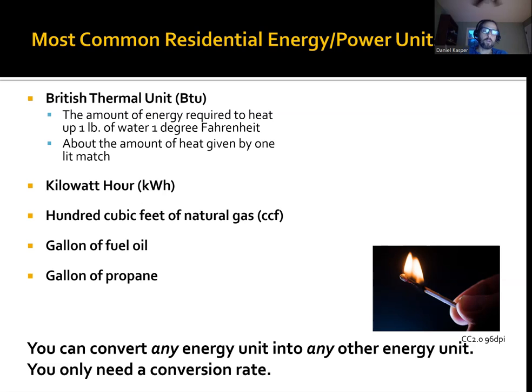For our purposes, it doesn't matter if the water is, let's say you have 1 pound of water that's 100 degrees. If you add 1 BTU to it, it's going to be 101 degrees. In order to drop it to 99 degrees, you need to subtract 1 BTU. Okay, so 1 BTU per pound. Let's say you have 1 gallon of water, which is about 8 pounds, at, I don't know, 50 degrees. If you want to increase that by 1 degree, you have 8 pounds. To go 1 degree requires 8 BTUs, and so on. So it's a 1-to-1.